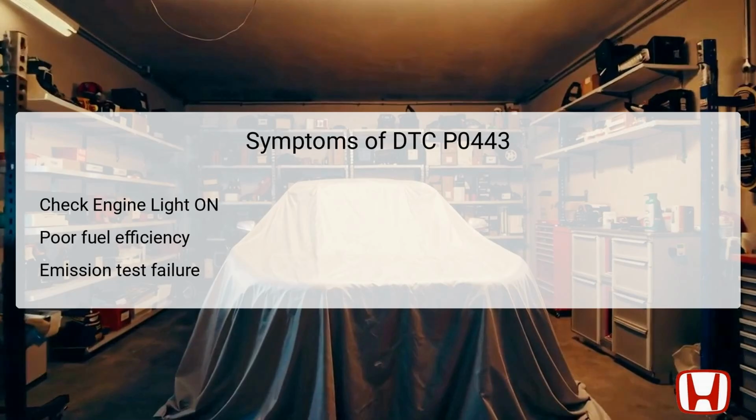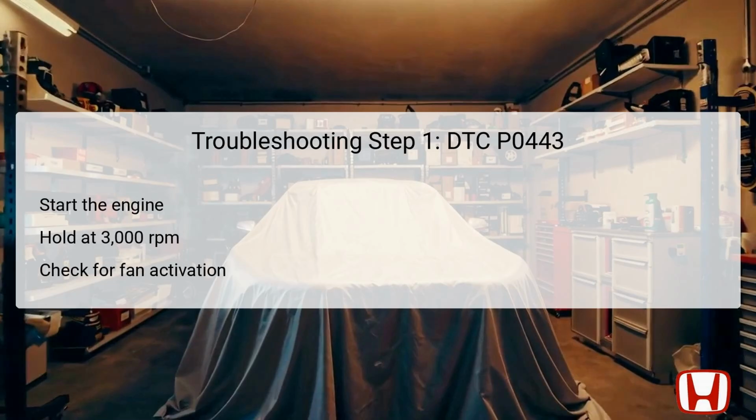The first step in troubleshooting DTC P0443 involves starting the engine and maintaining an engine speed of 3,000 revolutions per minute, RPM, without any load. This means that the continuously variable transmission, CVT, should be in either park or neutral, and a manual transmission should be in neutral.